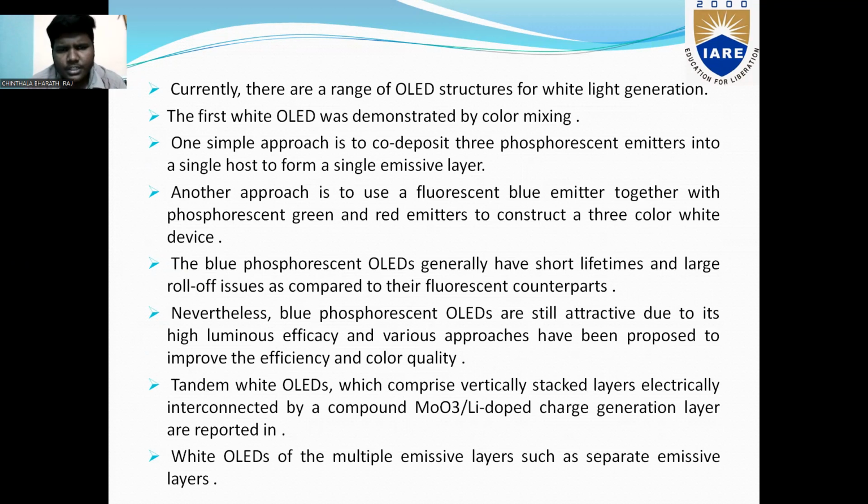One simple approach is to co-deposit three phosphorescent emitters into a single host to form a single emission layer. Another approach is to use a fluorescent blue emitter together with phosphorescent green and red emitters to construct a three color white device. The blue phosphorescent OLEDs generally have a short lifetime and large roll-off issues as compared to their fluorescent counterparts.